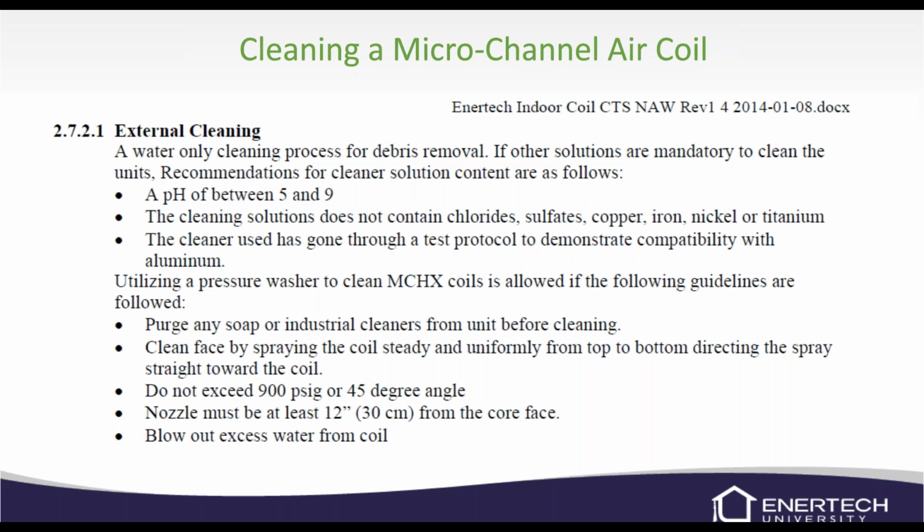Microchannel coils, if you need to clean these, they're not the easiest to clean. It's a water-only cleaning process. If you do need to use a solution, you've got to check the cleaner to make sure it has a pH between 5 and 9. It doesn't contain chloride, sulfates, copper, iron, nickel, or titanium. If you're not real sure about a product, give us a call and let us know. You're not really supposed to use coil cleaner on them. They're acid-based. You can use something like a dish soap.